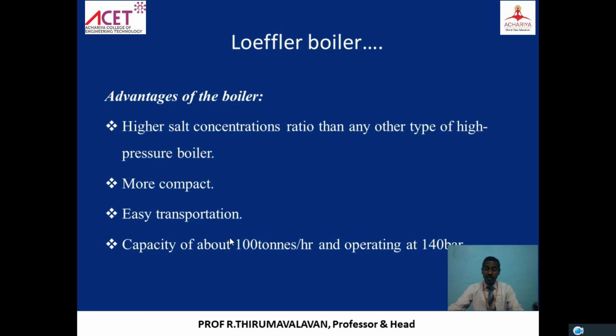Benson is the highest capacity, with high pressure and high temperature. Here it is 140 bar only. If you go for a Benson boiler, it is 170. Capacity is high and pressure is also high in the case of Benson boilers. So the Lamont boiler is used for small scales, the Loeffler boiler for medium scales, and for high capacity they go for Benson boilers.